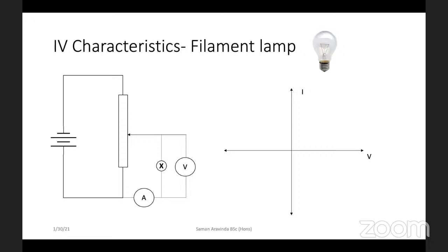That's when resistance starts to increase. Resistance increases. What will happen to the gradient of the graph? The gradient will reduce, it will flatten. So this will be the graph, isn't it? See, the graph's gradient reduces. That means resistance increases, because the gradient is not resistance, it's 1 over R, because I over V is the gradient.